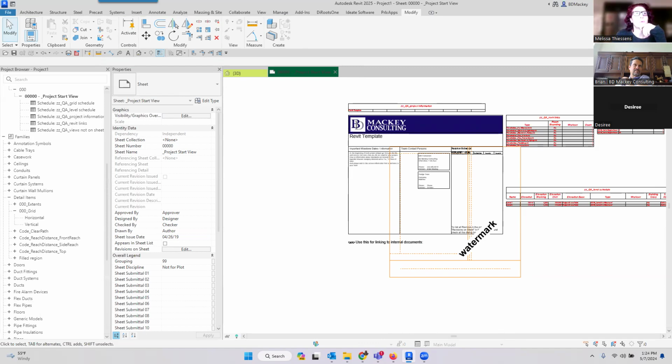So Nick put in something that doesn't really seem like a question. Nick's saying there's a 10-second lag if he clicks out of Revit, like to Bluebeam or email. When he clicks back into the Revit drawing area, you get the spinning wheel of boredom for 10 seconds. The only way he found around this is to click the topmost part of the Revit window where the project title is, then it doesn't happen. It occurs on all versions of Revit on his current machine, not when he remotes into the office. So if you click out of the print dialog and come back to Revit, you're getting the spinning wheel of death unless you activate Revit up here.